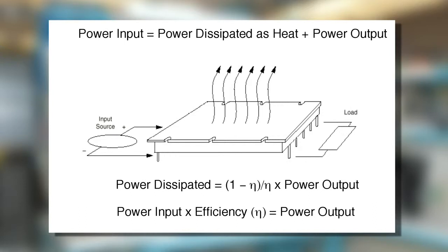The heat generated inside the module will be dissipated or removed through the metal base plate, which is part of the module case or packaging. The base plate is thermally coupled to the internal power dissipating components, to the power devices, but it is electrically isolated from these for safety reasons.